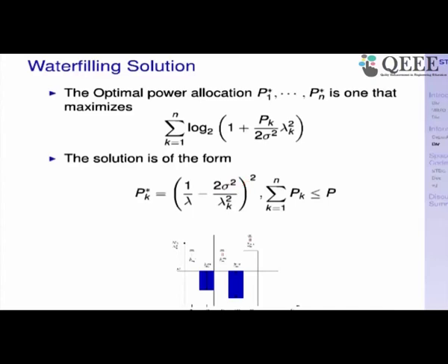Yeah, PCP, we are considering high SNR to see that at high SNR, it really doesn't matter whether you know which direction to transmit or not, because the SNR is so high that it is sufficient to transmit equal power in all directions. So if you have a very good SNR, there is no point in asking the receiver to send the channel information to the transmitter. So that saves additional work. That's why it is important to see what happens at high SNR. That's why we have addressed that.